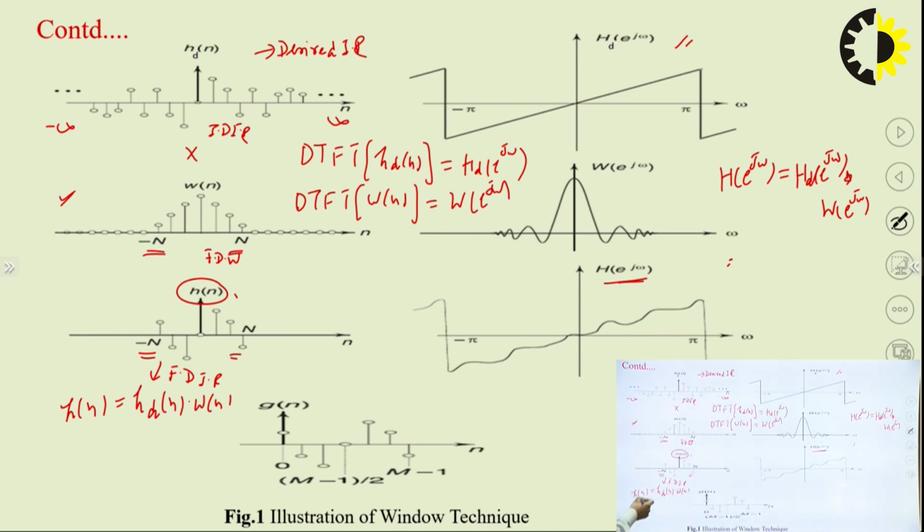One important thing is that the impulse response here is of finite duration, but it is non-causal. So we have already discussed that non-causal filters cannot be realized. So we have to make it realizable. How can we make it realizable? We simply delay it by n samples. If we delay h[n] by n samples, this sample will occur over here.